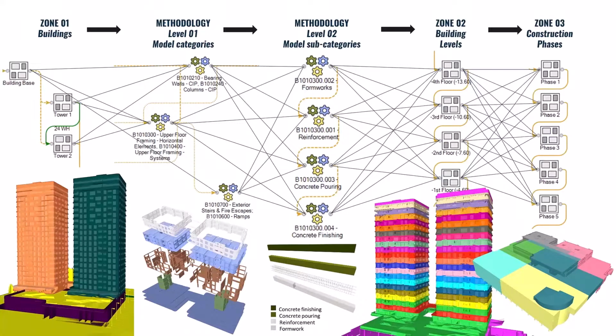definition. Spatial project organization means that we always organize our construction works regarding the spatial structure of our building. So if we have multiple buildings, we are going to divide our schedule by buildings. If we have multiple stories on every one of these buildings, we are going to define the subtasks for the stories. Also, if we have multiple zones on one story, we are going to define these zones or phases as well. This spatial organization is project specific.